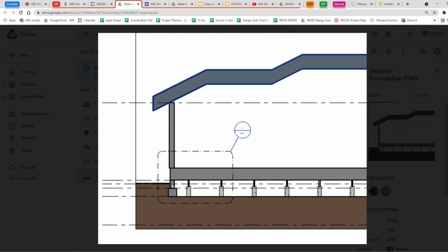And the stem wall is basically just so you can get up above ground, because in most parts of the country, you want to avoid water and pest damage to your floor system and your walls. And to do that, it'll usually be 6 inches from the ground to your floor system. Now, some places, because of flooding and water and stuff like that, these just transfer right on across, and these are pure blocks also. But around here in the valley, you're going to see it like this. Okay? So that's a section view.